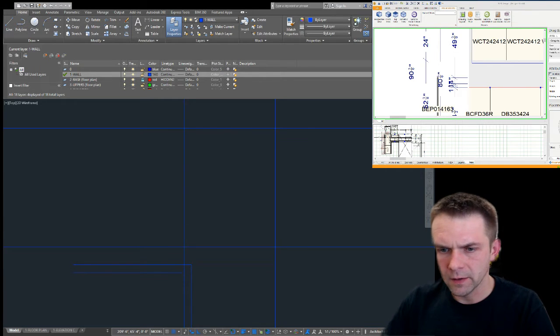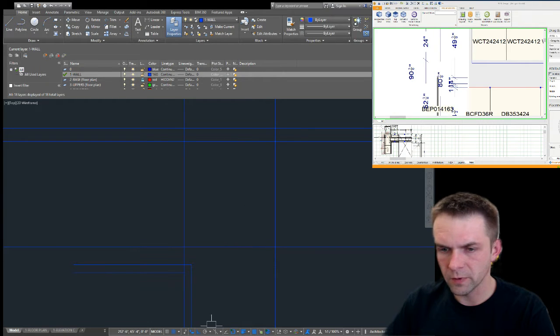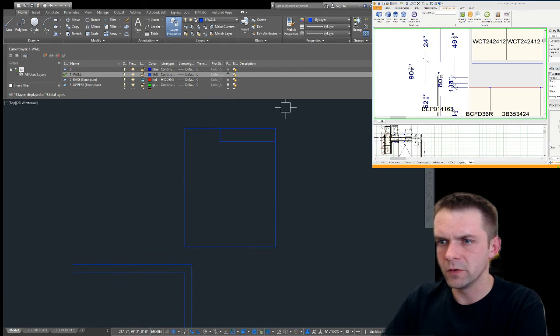The bulkhead is 6 feet. 6 feet times 12 plus 8 is 80. Offset 80. And this way goes 36 plus 9, 45. Offset 45. This way REC for a rectangle. We can do that. Then we go fillet. Click. Fillet. We can erase these guys.